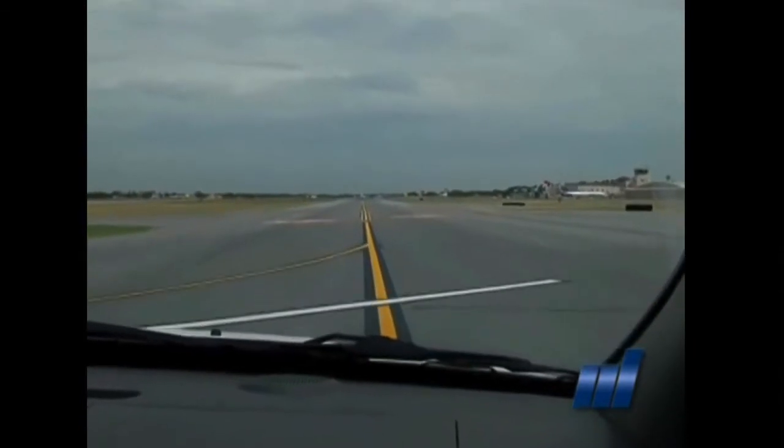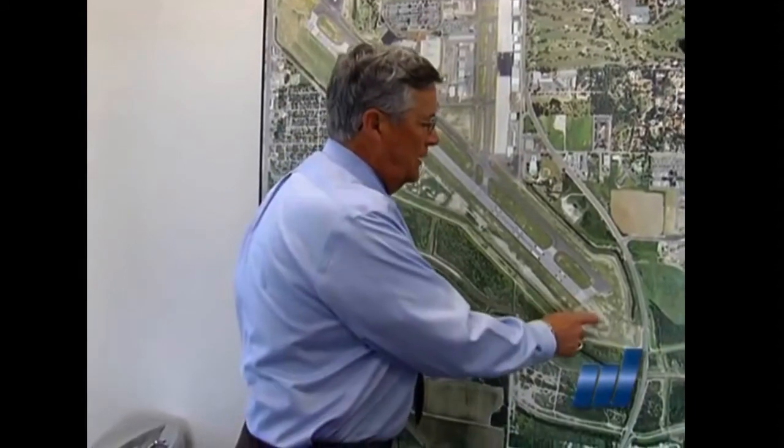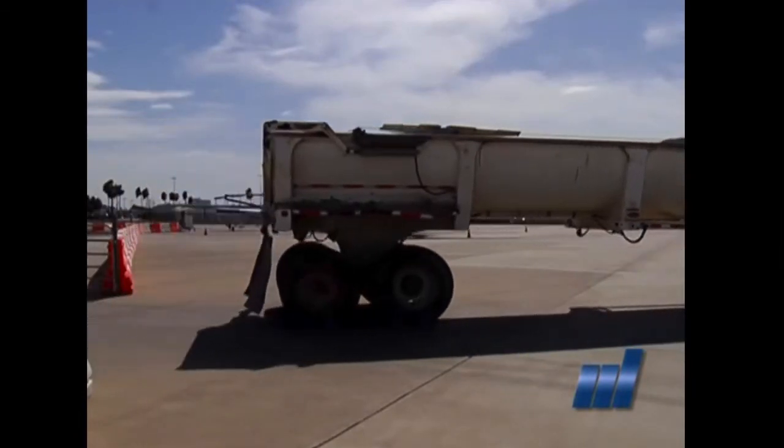The other alternative is a $10 million fix with more benefits for the airport. It includes installing EMAS. By putting what we call engineered material arresting system down here, we can actually, in effect, increase the length of our runway. Because when you put that EMAS down here, it's concrete that when an airplane goes on it, it crushes and it'll sink in and it'll stop the airplane. And so by putting 300 foot of EMAS down here, it has the effect of acting like 1,000 foot of safety area. Essentially, more runway translates to farther destinations for airlines.